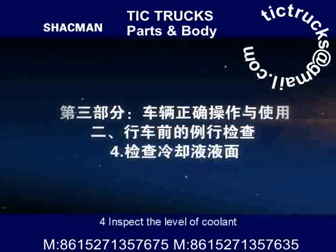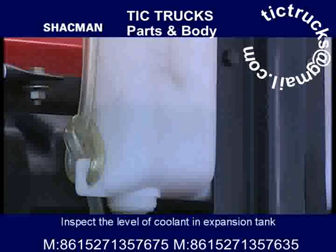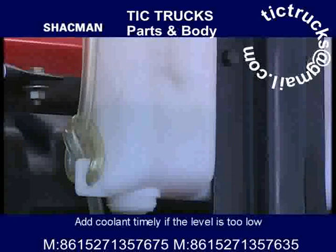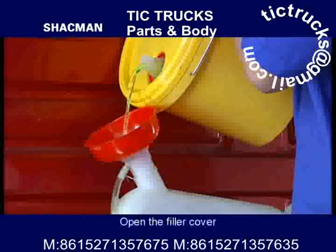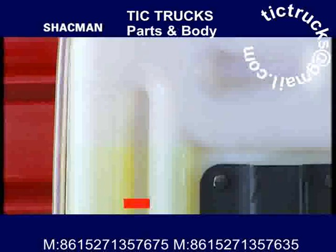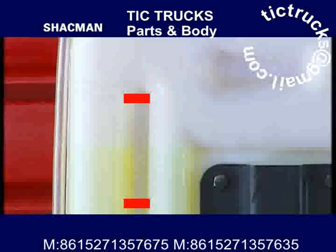4. Inspect the level of coolant. Inspect the level of coolant in expansion tank. Add coolant timely if the level is too low. Open the filler cover and fill the coolant to the level between the minimum and maximum marks.